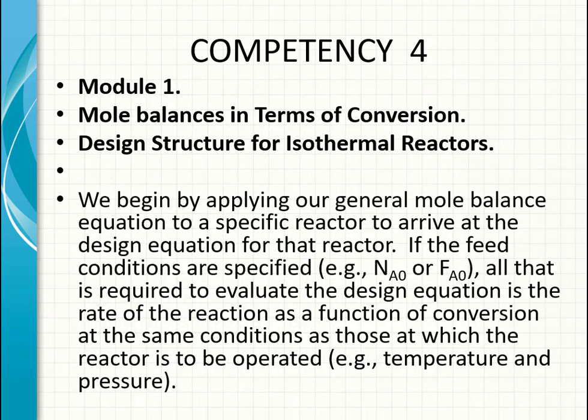Module 1. Mole balance in terms of conversion, the design structure for isothermal reactors. We begin by applying our general mole balance equation to a specific reactor to arrive at the design equation for that reactor. If the feed conditions are specified, could be NA0 or FA0, all that is required to evaluate the design equation is the rate of the reaction as a function of conversion at the same conditions as those at which the reactor is to be operated. That means temperature and pressure.